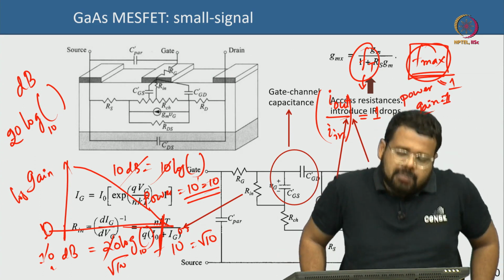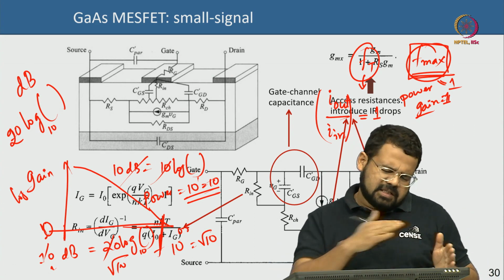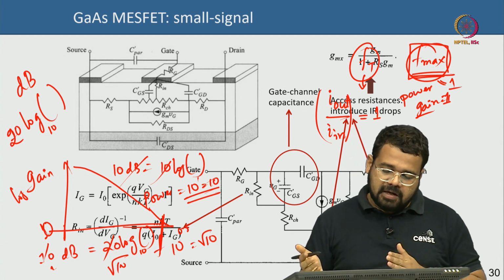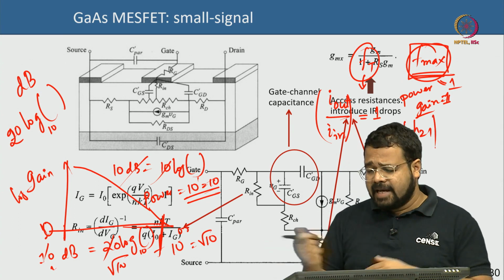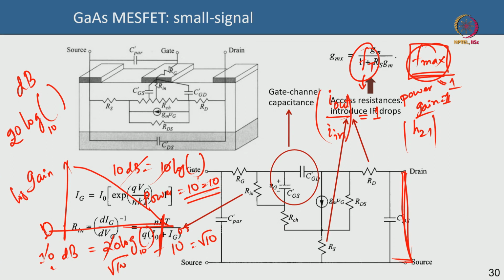So, essentially you have to measure the scattering parameters, S parameters, and convert them to Y parameters. These are some two-port network analysis. Then you go to the H parameter, the hybrid parameter, and you define the gain as H21, which is your small signal gain. To find the gain, essentially you have to short the output: the drain and the source have to be shorted. You short the output drain and source, and so you will shunt out a lot of capacitances there.